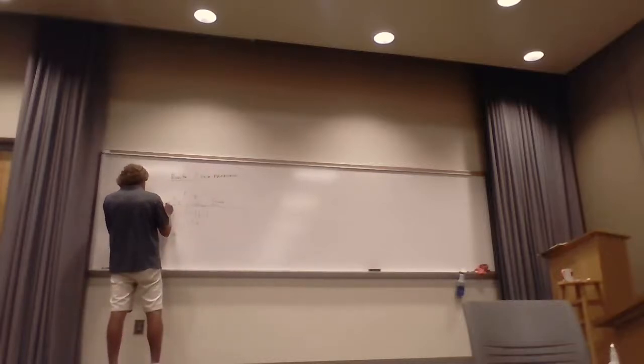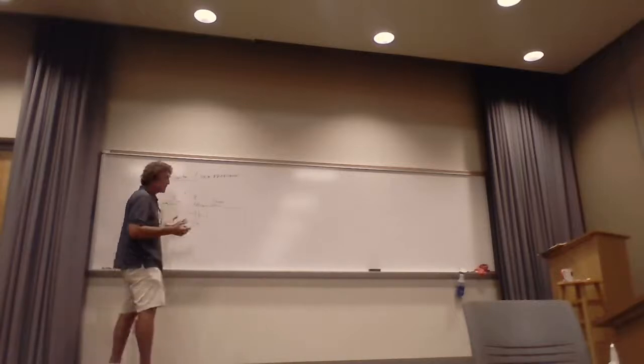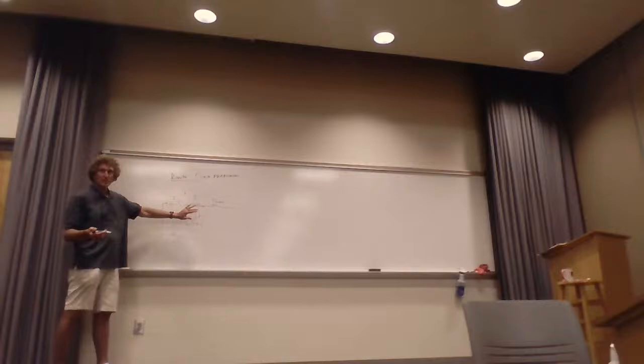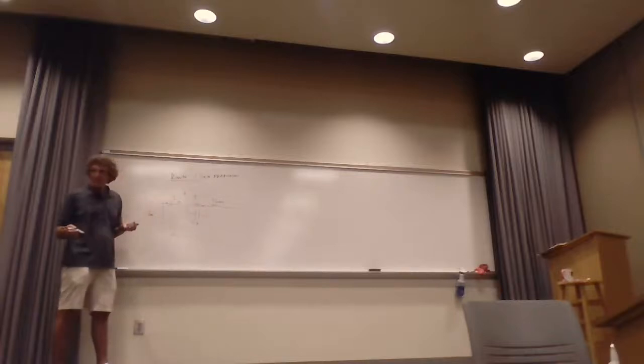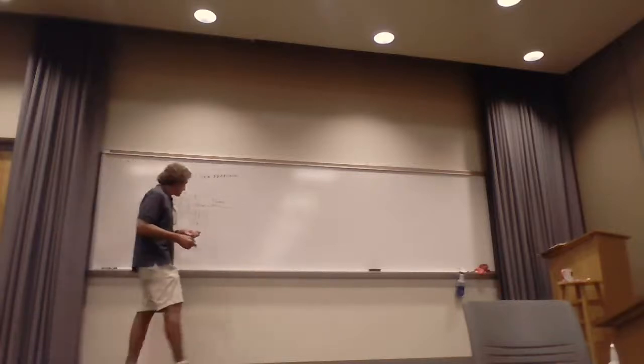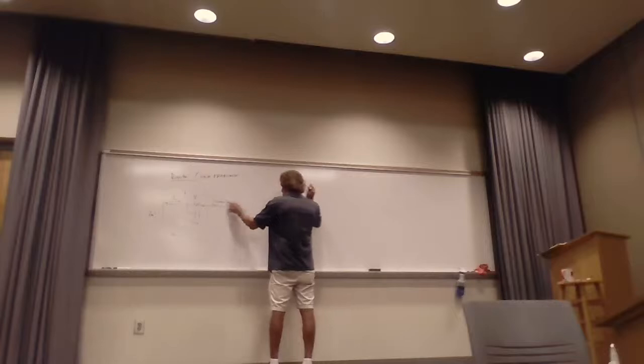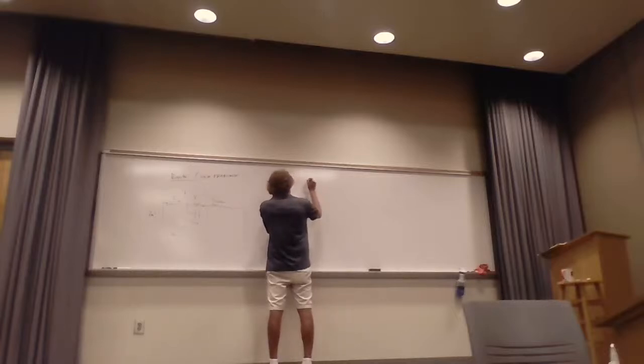So if we wanted to know what Z is here, right? If you look at it at very low frequencies, an inductor looks like a short circuit and a capacitor looks like an open circuit. So it is just the resistance, right? But if we wanted the actual value here, we would say the Z itself would be equal to j omega or s. I'm going to use s, where s really is given as j omega plus some sigma.